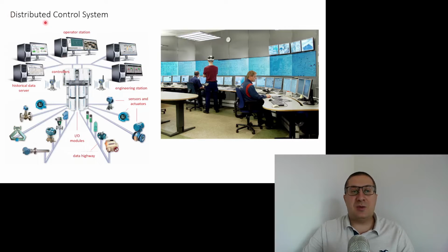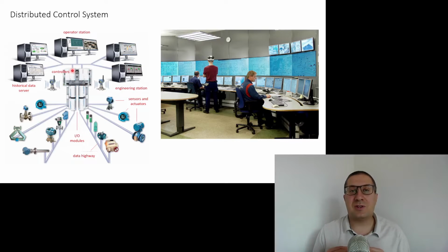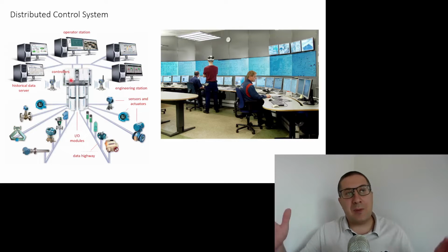Yeah, the distributed, right? This is the important word here, distributed. It is distributed because we don't have one master server, one master controller that controls the whole plant. We have a set of controllers, and each controller controls part of the process.